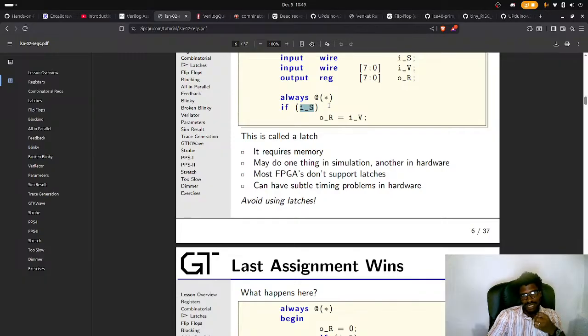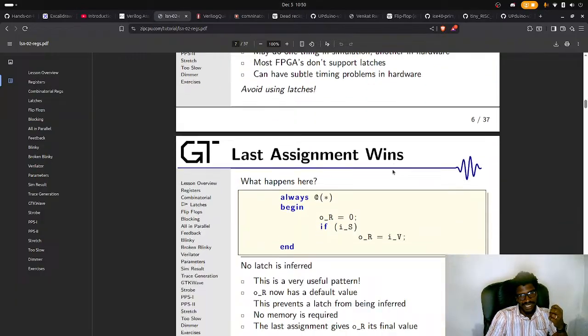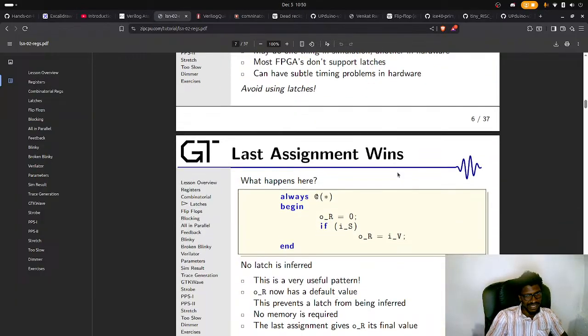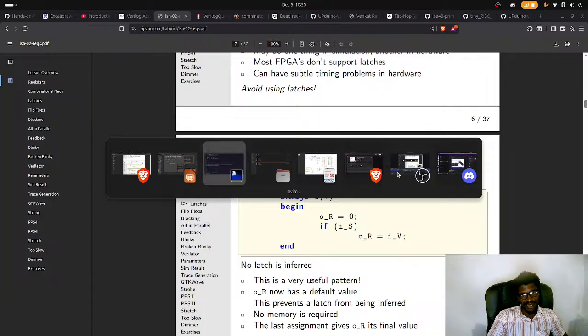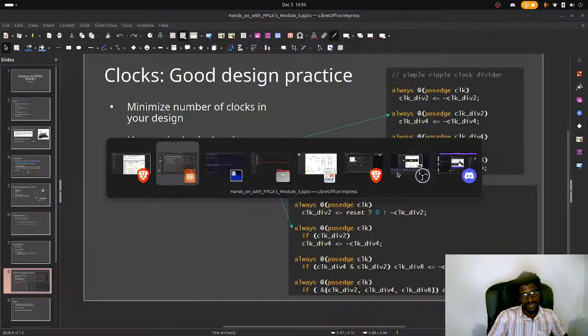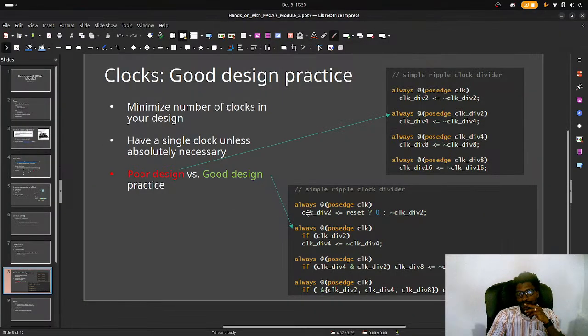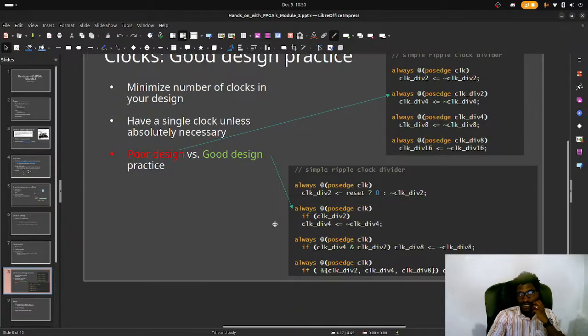Okay, so basically what is being said in both of the things is to avoid inferred latching. Always do explicit sets, and then use those explicit sets while you're doing your settings and your assigns and your de-assigns. Yeah, de-assigns is an actual thing. So don't use implied latches.